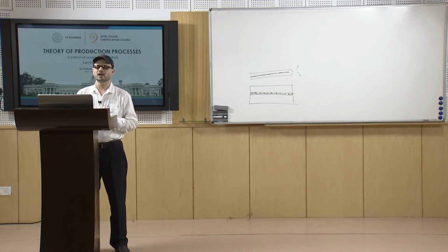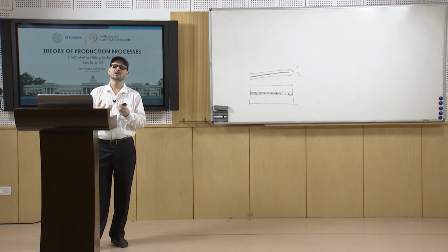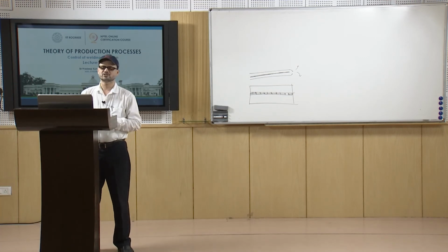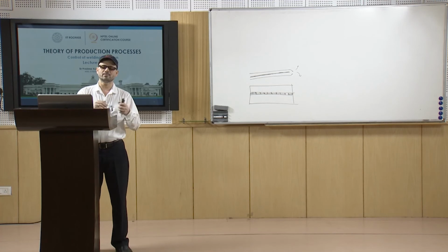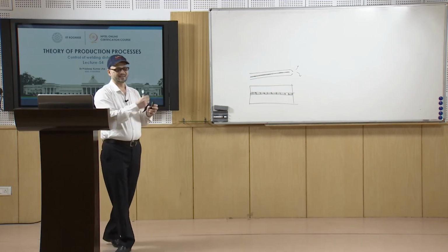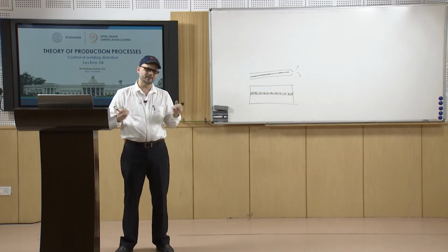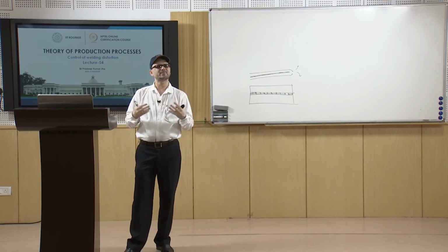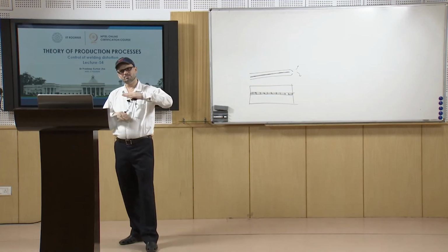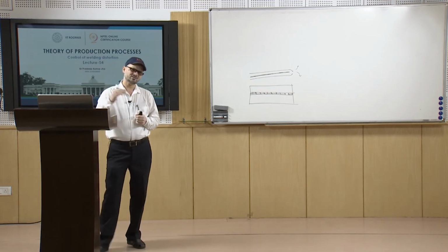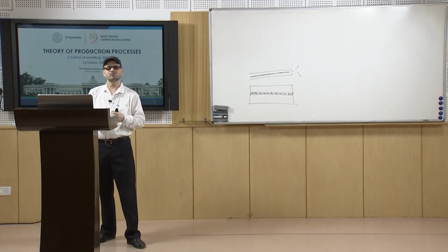We can also use a water cooled jig many a times, where copper tubes are brazed to the copper holding chamber, and then water is circulated through these tubes, and most of the heat is taken away by this water. The purpose is that when you have a thin sheet, it is very difficult for it to carry that much heat in such a short time, and because of the heat it may buckle or distort. So we place some conducting material that allows the extraction of heat fast, and the distortion will be a minimum.